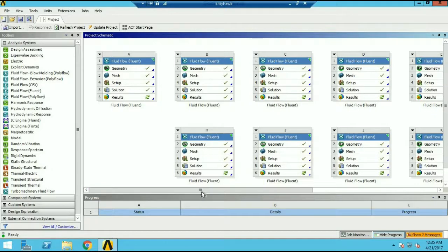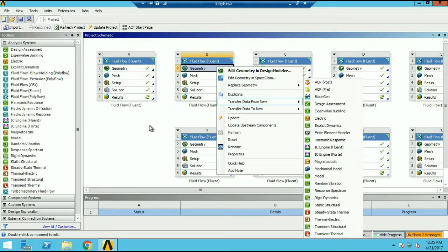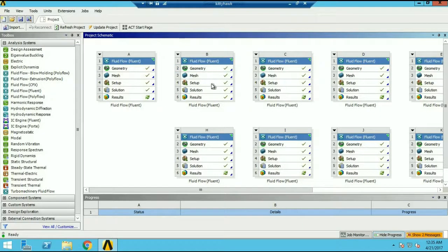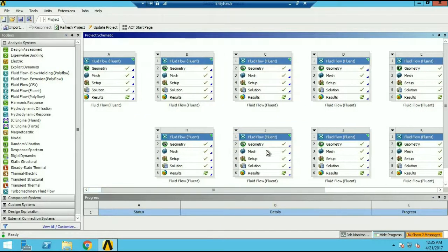So yeah, again, I imported the base geometry and then did the rotation each time, made the enclosure. You have to rotate before you make the enclosure. Boolean, meshed it. You actually see in these notes, sometimes I write other little notes. I noticed that with some different rotation angles, you had to use different meshes.